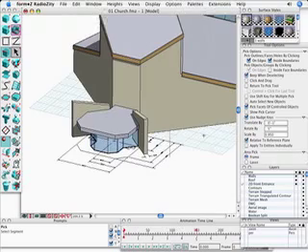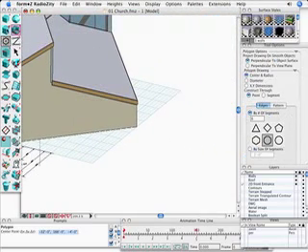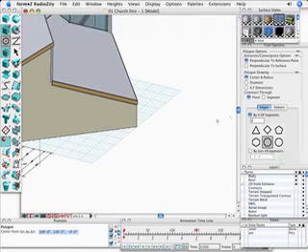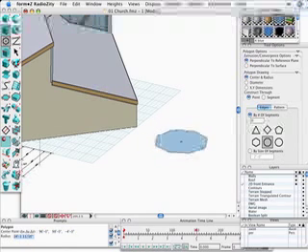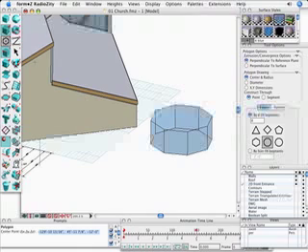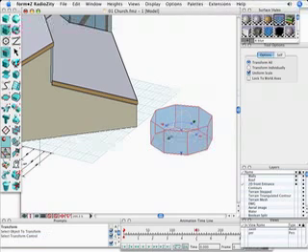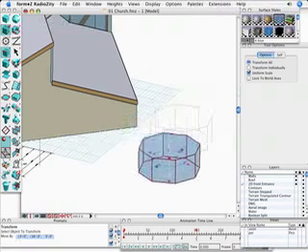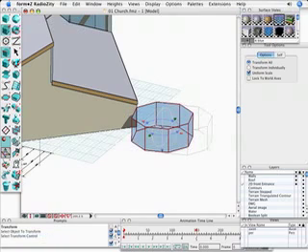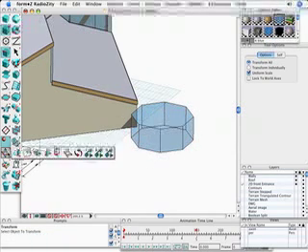As we move to the side, we're going to create a different space here by, instead of creating the outside volume and working our way in, we're going to start with the inside volume first. So we'll just create maybe a polygon pattern, type in values for the inside radius if we want, and for the overall height. And there's a transform tool, which allows us to move, rotate, and scale all with a single tool. So we'll move our space more closer to the side here and rotate it, scale it, reshape it, all with one single tool now.